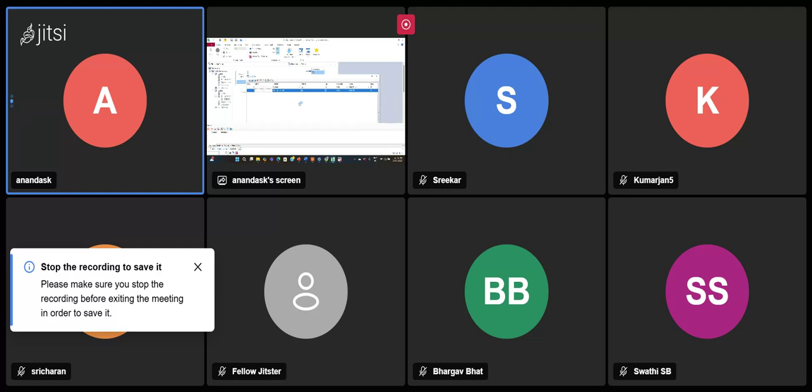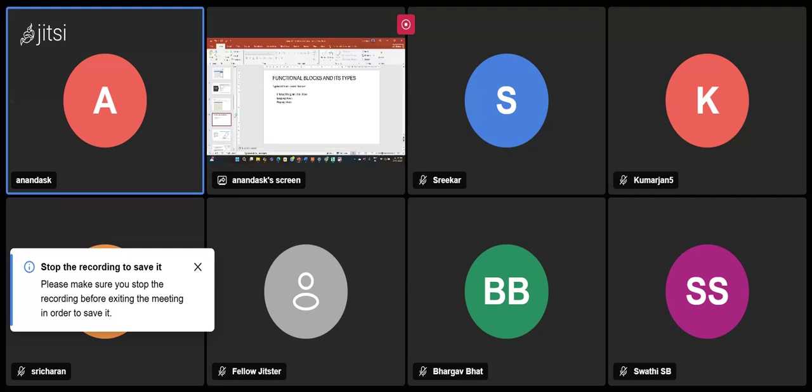But if you have actual CAN messages, you can see what is there in the data, so you can simulate those values here. So we go to how to add functional blocks to the simulation. With the interactive generator block, you can configure and send messages while a measurement is running. So this is what we did now.